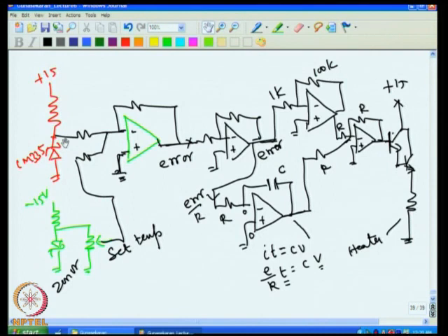This is good, because if we had the difference, if there is an error, we are seeing that this produces a secondary effect, in the sense that if the ambient temperature changes, then the error also changes, and that creates a problem. It appears as if the controller is slowly drifting with the ambient temperature. This problem is solved by adding an integrator.